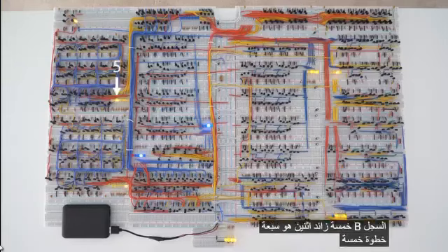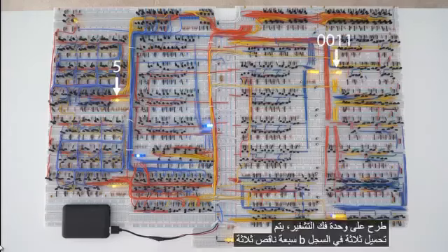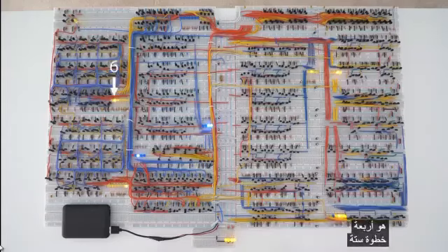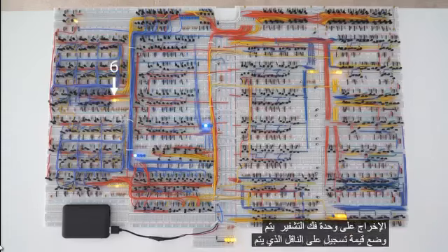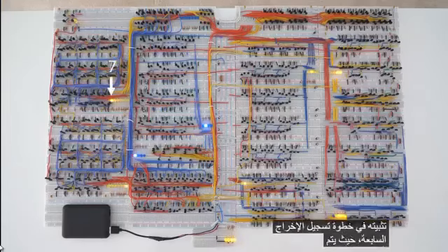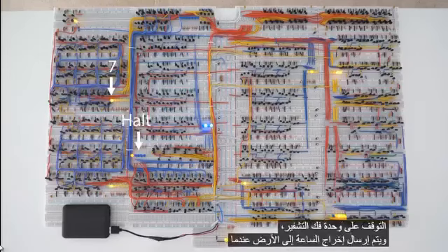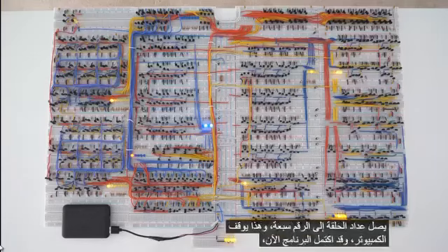Step 5. Subtract is on the decoder, 3 is loaded into register B, 7 minus 3 is 4. Step 6. Output is on the decoder, the A register value is placed onto the bus, which gets latched into the output register. Step 7. Halt is on the decoder. The clock output is sent to ground when the ring counter hits 7. This halts the computer. The program is complete.